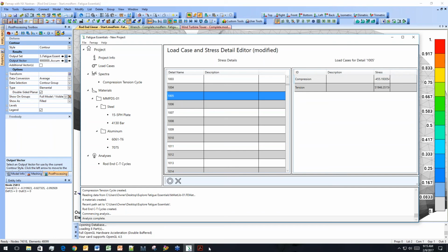What you have to be careful of is, if you're running a model with 1 million nodes and you have a complex spectrum, you need to run a rainflow or a peak counting or range pair or whatever on each of those nodes. So I think in theory, is it possible? Yes. I think that the preferable approach would be to look at your model and see where your problem areas are going to be and narrow your area of investigation down to areas where you suspect that damage may be greatest. I think that's the preferable approach.